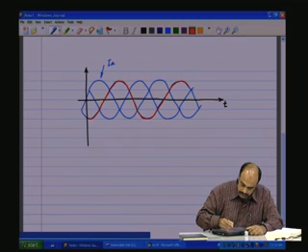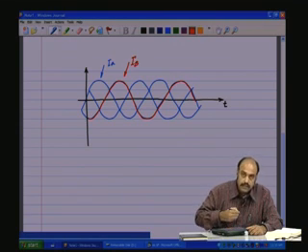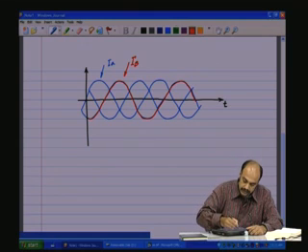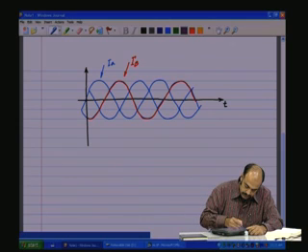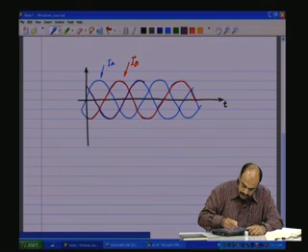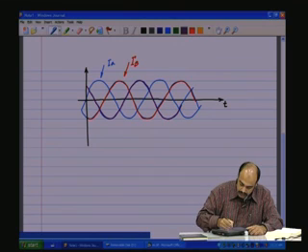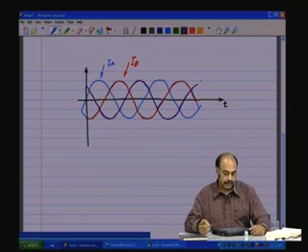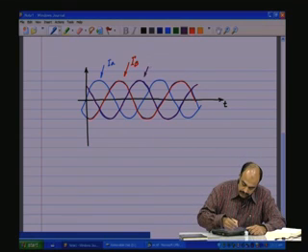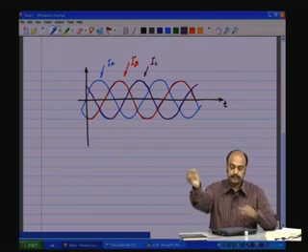So that is our B phase current IB effective value, and then the C phase current is given by the violet. So it comes in this fashion, which is 240. You see that it is now cutting the 0 and going positive 240 degrees with respect to the A phase. So these are the three phases IA, IB, IC.